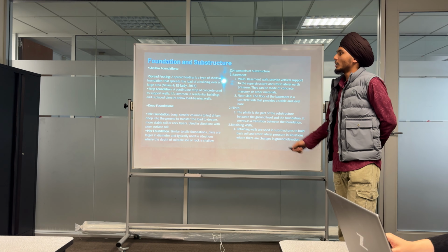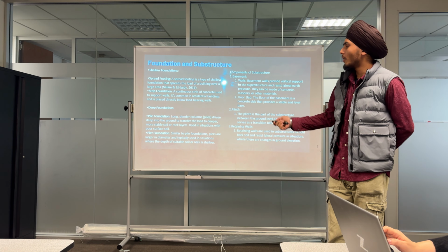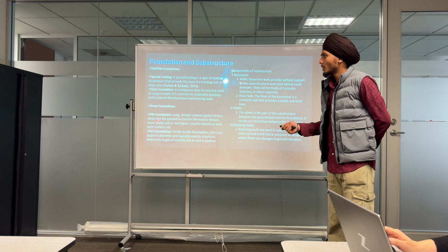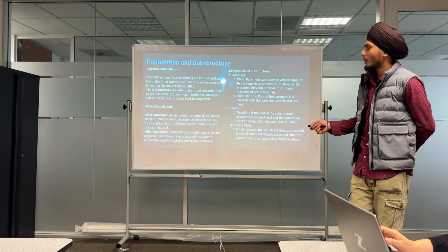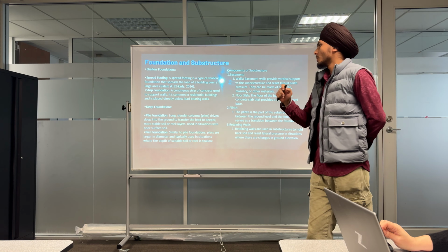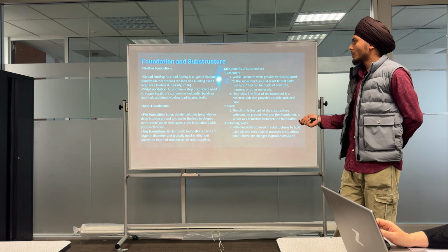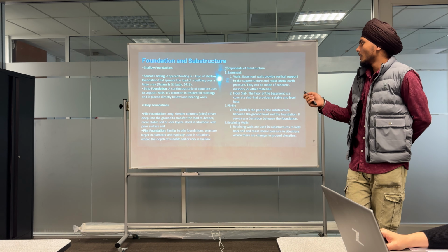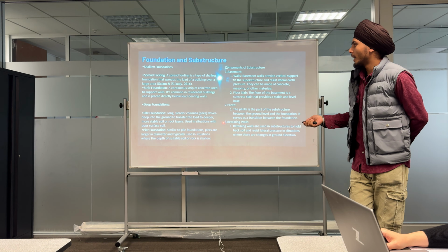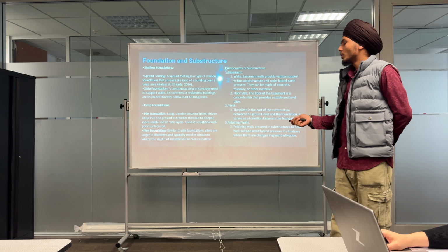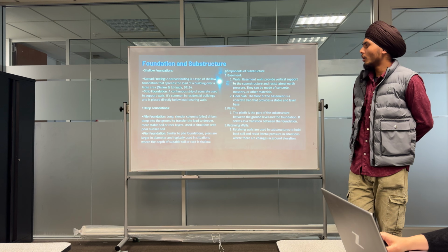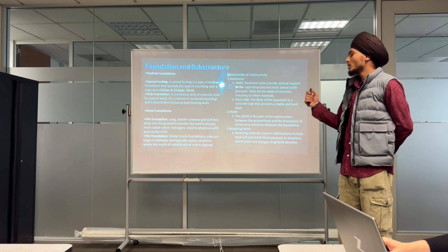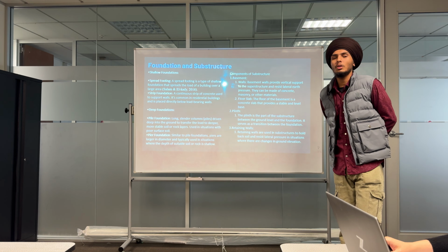And the second type of foundation is deep foundation. Deep foundation covers 2 foundations, like pile foundation and pier foundation. What is pile foundation? It is long slender columns, which we call piles, driven deep into the ground to transfer the load to deeper, more stable soil or rock layers, used in situations with poor surface soil.